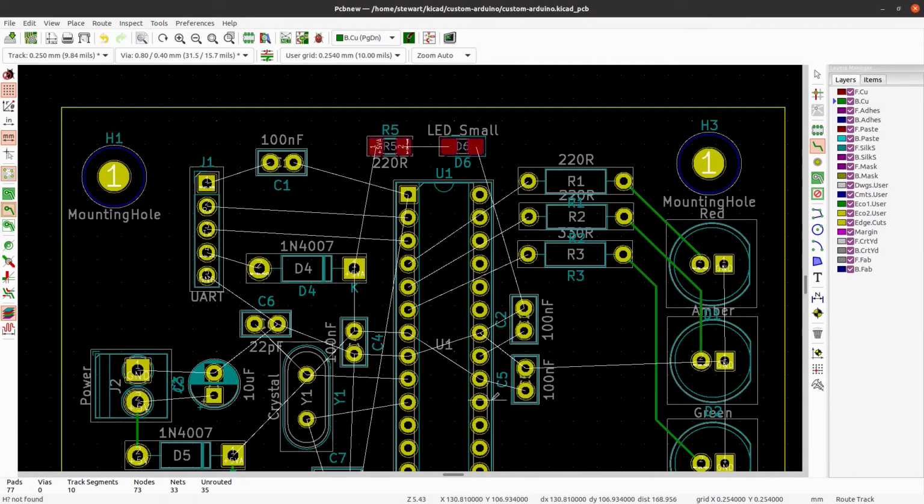For these capacitors that are smoothing capacitors, I want them really to be as close as possible, as short as possible from here. So even though there's going to be ground plane, I'm going to try and wire these pretty much directly into here.